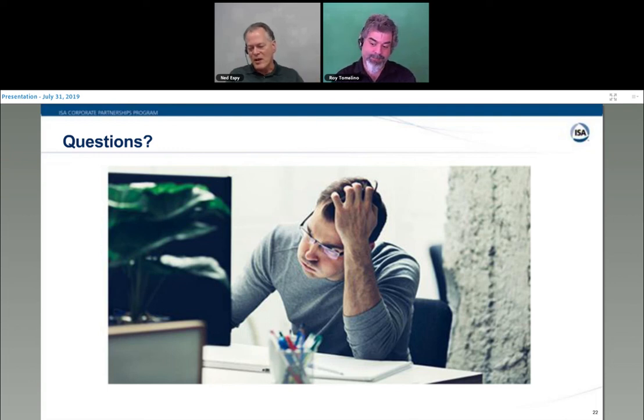So in Roy's example, all he had to do was fix the zero shift, and to save time, we didn't do a span adjustment because we knew it didn't need it. But I would say more often than not, you need to do both a lower trim and an upper trim and correct. Agreed. The lower trim is your zero shift, and the upper trim is, in effect, the slope. You're correcting it if there's a slope in the calculation. Yep.